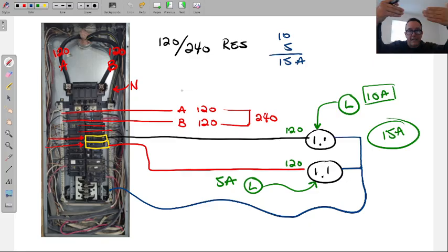Breakers get hot physically during operation. But hypothetically speaking, let's say that charger will continuously turn off because it says it's too hot, which is not normal. The charger won't do it. The breaker will trip. The charger will go until it burns down. The breaker has to be the one that shuts the circuit off. Now, if you have an old panel that doesn't trip, therein lies fires. This is why we have fire departments.